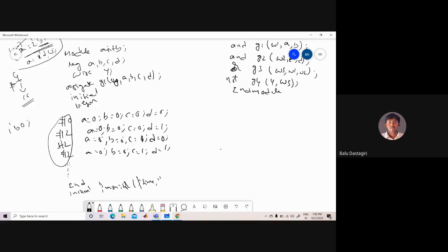For example, if you are giving #2.1 and using $time, only 2 will be printed. If you want the time to be plotted with decimal points, we have to use the real time. I have taken #2.1; if I am using $time, it will not consider the decimal point. In order to consider the decimal point, we have to use $realtime.